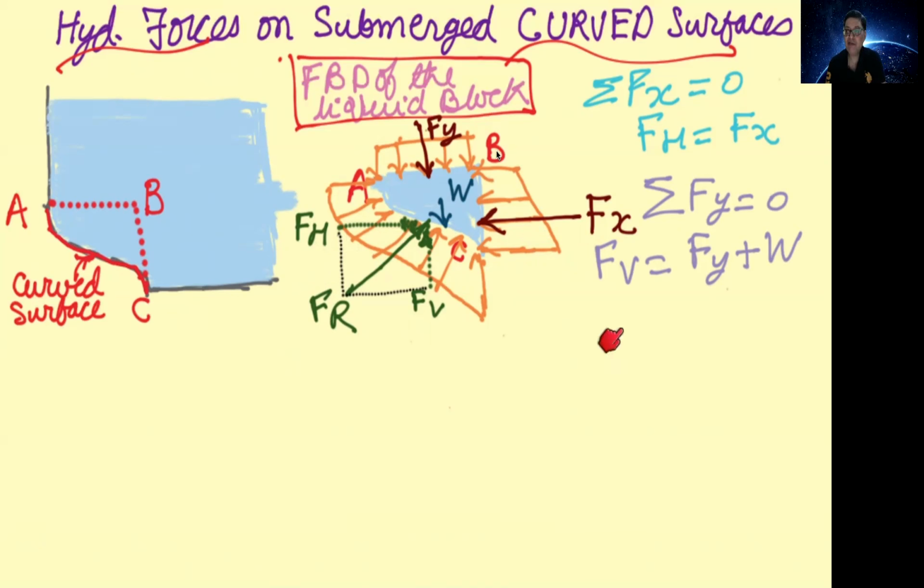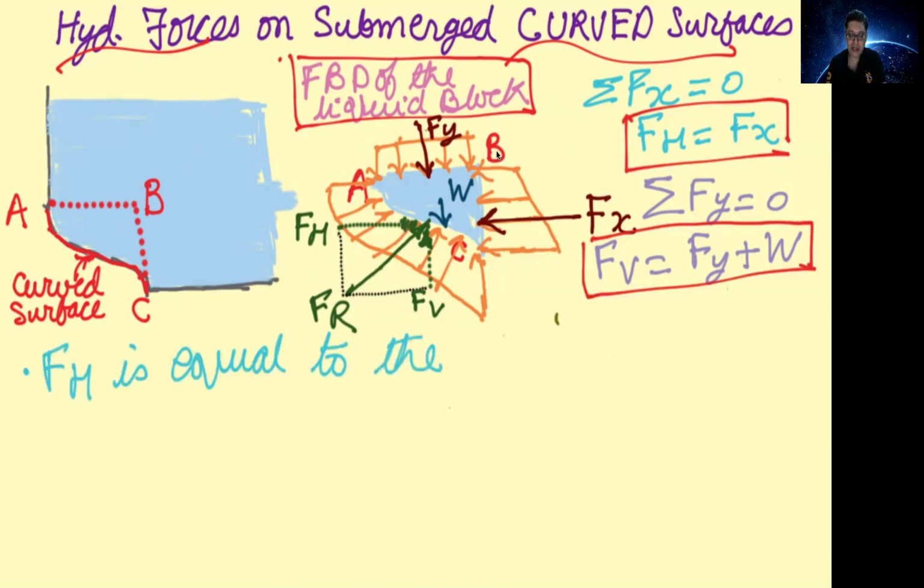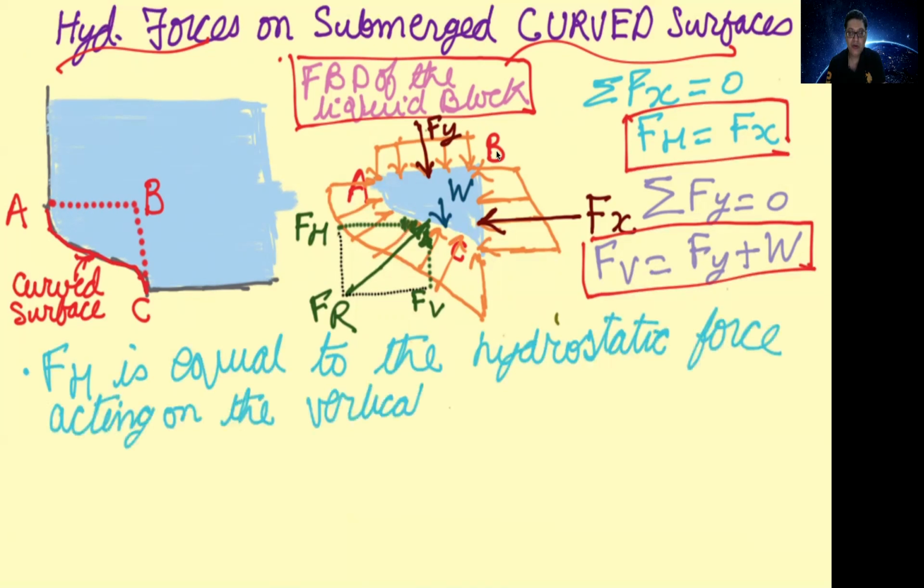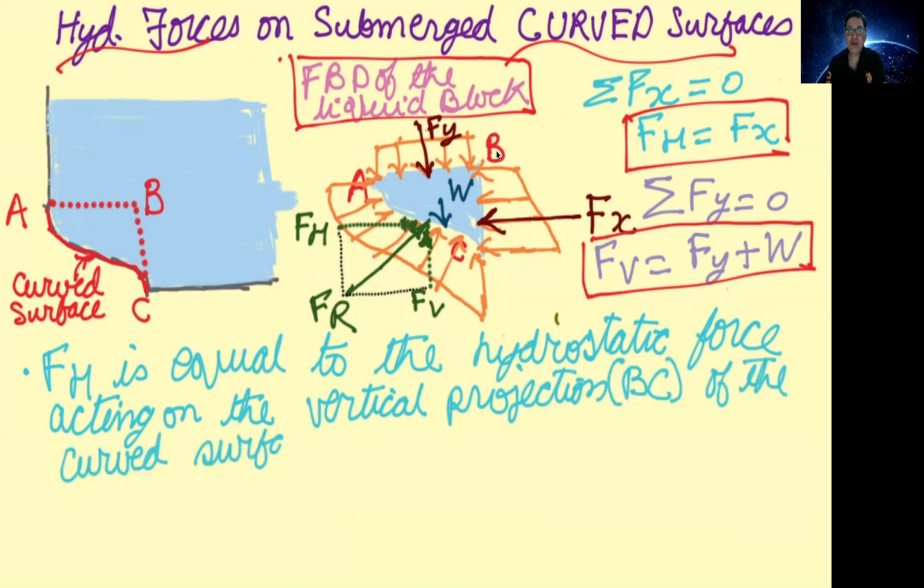So you get Fv equals Fy plus W. Finally, this expression leads us to a statement that the horizontal component of the hydrostatic force acting on the curved surface is equal to the hydrostatic force acting on the vertical projection.